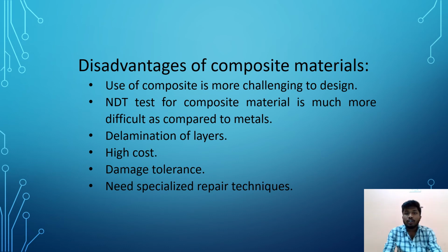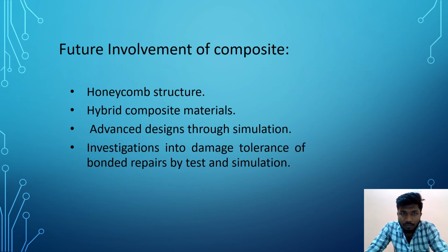What are the disadvantages of composite materials? Composites are more challenging to design. NDT testing for composite materials is more difficult compared to metals. The layered elements have high cost and damage tolerance issues, and we need specialized repair techniques for the repair of composite materials.